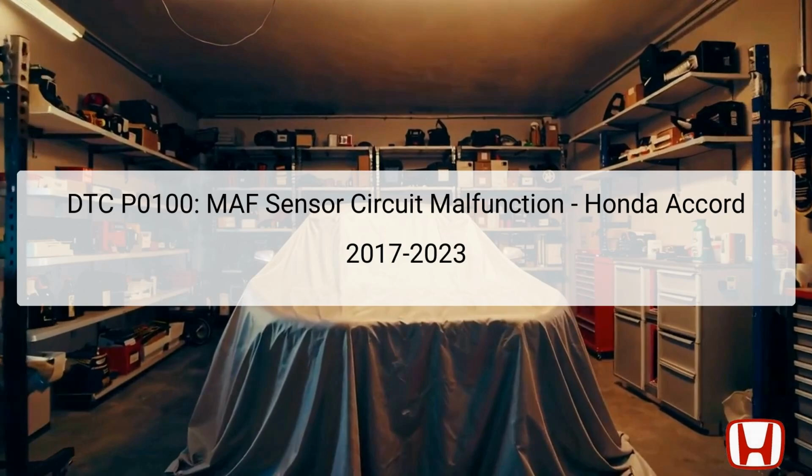DTC, or Diagnostic Trouble Code P0100, indicates a malfunction in the mass airflow (MAF) sensor circuit of the Honda Accord from model years 2017 to 2023. This specific error suggests that the engine's control unit is receiving improper signals from the MAF sensor, which plays a crucial role in measuring the amount of air entering the engine.